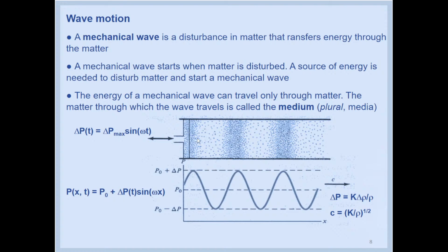And where is it moving? It is moving into the cylinder that is filled with air. The cylinder is open from one end, and consequently when the piston goes into the cylinder, it compresses the air particles. When it goes back, a rarefaction area is developed. After several oscillations of the piston, when we stop this process and make an instant picture, we obtain this distribution of the pressure in the air in the cylinder. And this may be represented as this graph.